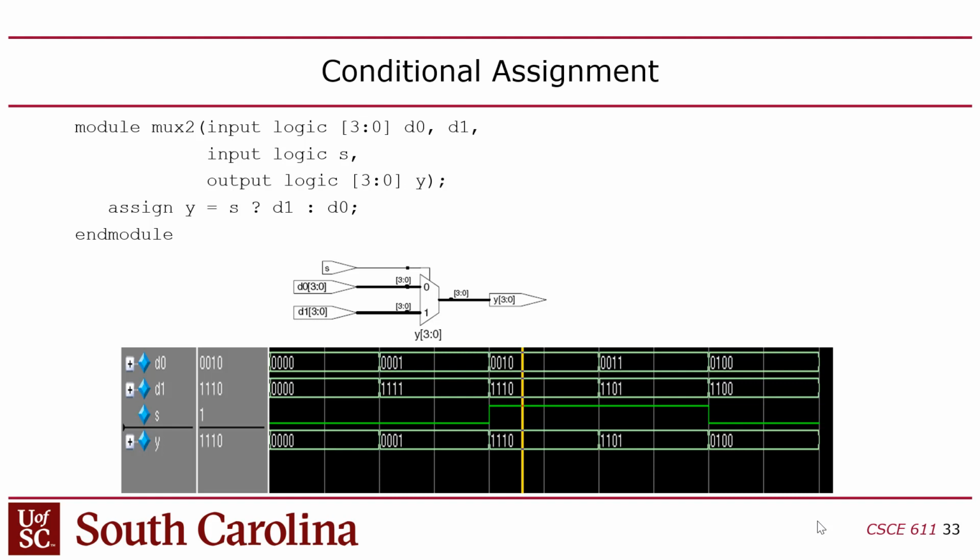So that very naturally maps into a multiplexer where the condition is the select on the multiplexer, and then the middle input here is the 1 input on the multiplexer, and then the second one is the 0 input on the multiplexer. So in your CPU design, you're going to have a lot of multiplexers because multiplexers are fundamentally how you steer data around to create data paths, right? It's also how you multiplex inputs. So for example,